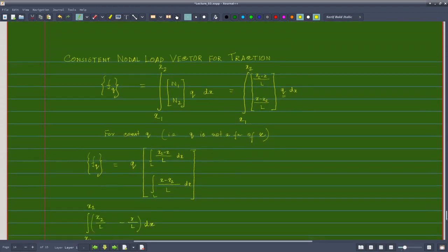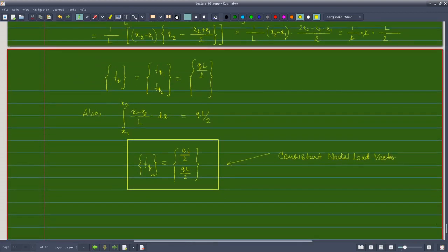And we have seen that by two noded element I can find out the value of the element stiffness matrix for this two noded element. Now one question arises, if I have a long bar, I know that in an axial deformation problem, from our analytical solution my actual deformation varies cubically over x, but here we are taking the variation of displacement over the element as linear. So if I use a single bar element for a bar, then there will be some errors. My results will not be very correct.